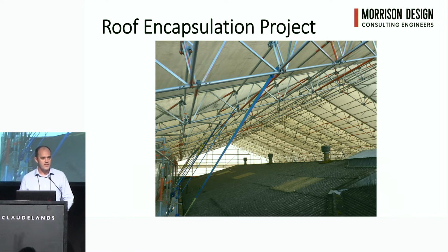Another thing to think about is sometimes we get requests for the scaffold to be completely independent from the building and have no attachment to it. And this is something you need to be careful with those requests, because once the scaffold's no longer attached to the building, it sort of stops being a scaffold and it becomes a building in its own. So all the load considerations and all the calculations and design elements you might do for a normal building, you then have to do for your scaffold.